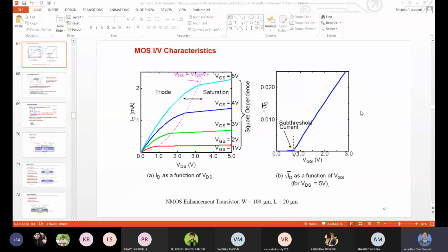So here I want to go one step further. If you have plotted a series of plots, after that you have to calculate threshold voltage, and also the channel length modulation parameter. So instead of so many plots, we require only one plot, the ID versus VGS plot. We are using 50 nanometer technology and it is working at 1 volt. VDD is 1 volt. So we will keep VDD equal to 1 volt and we will vary VGS from 0 to 1 volt, and we will plot ID versus VGS, and one plot will be there.